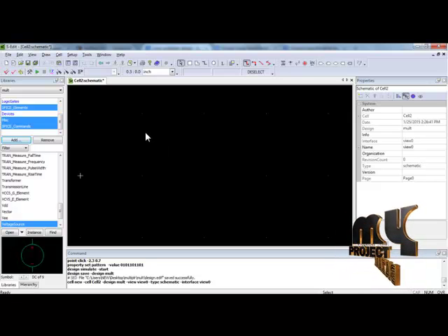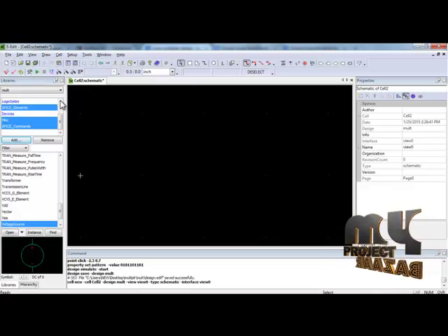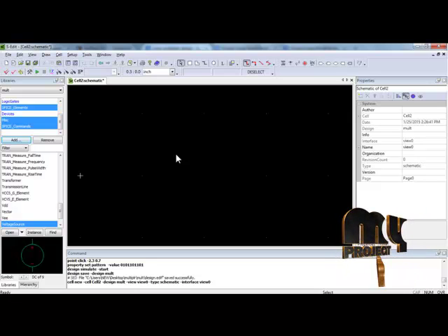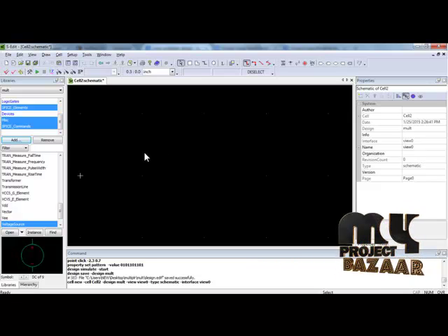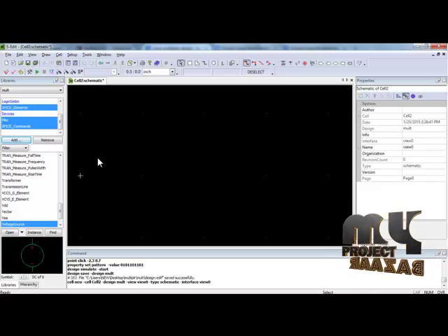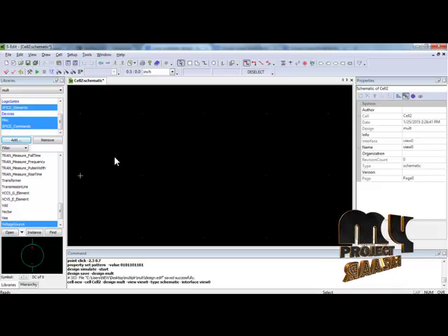The next process is to set up the simulation. This icon, when you press it, will lead you to setup simulation. In the setup simulation you have to set up the maximum time duration for the design, in nanoseconds. After setting up, we have to load the library files. Initially, for the design of CMOS circuits we need some CMOS components. Those CMOS components are contained in CMOS libraries. That means CMOS libraries contain the components required for CMOS design.